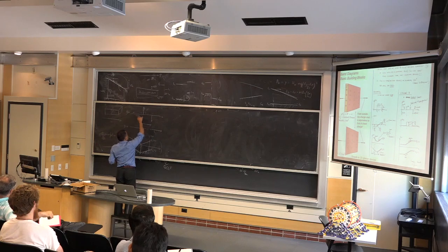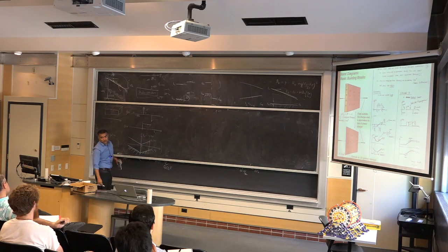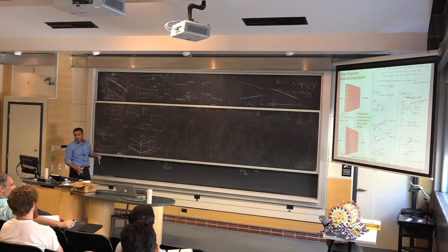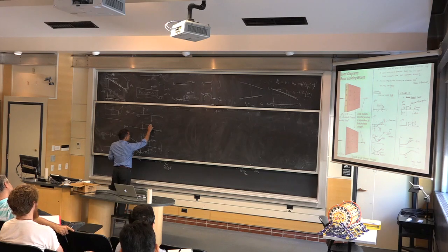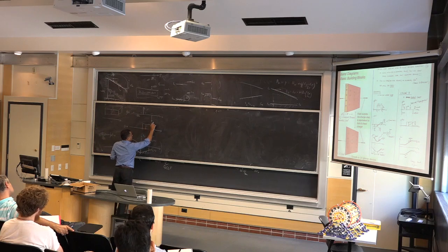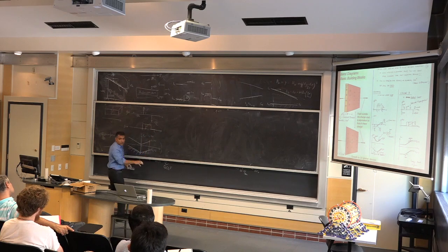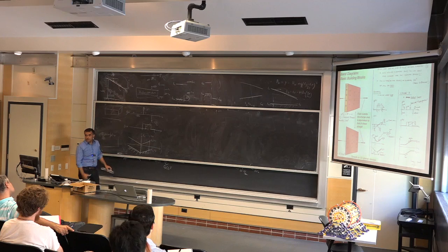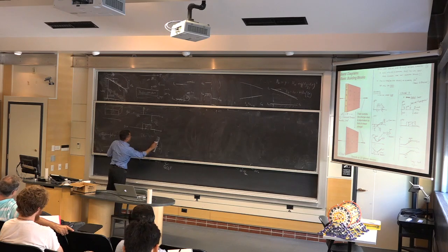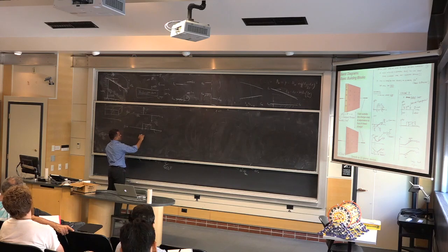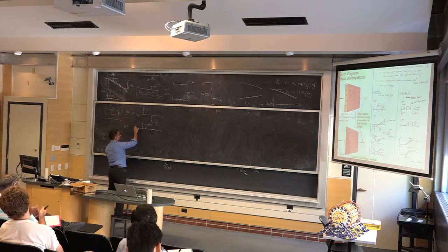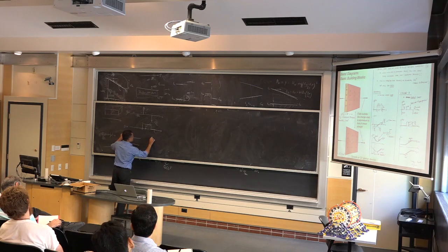But if they're exactly equal and opposite, the fields will cancel exactly outside the planes of the dipole. What you'll be left with is just the field inside, and that field will be exactly sigma by epsilon. It's twice that original field. You add it up, and when that happens, you can draw your energy band diagram and your potential. I think you can see what's going to happen. Nothing happens outside here. So outside there, the bands remain flat.